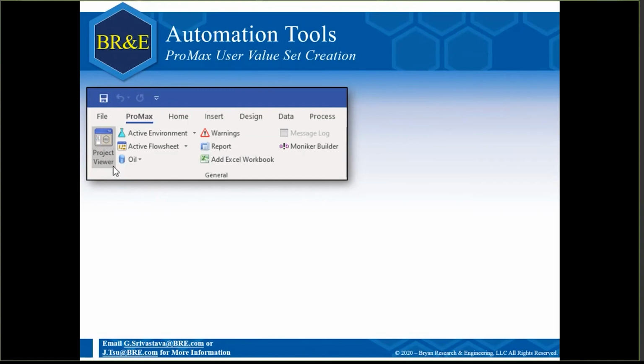We have added correlations that companies use, and even used this feature as a control panel with a bunch of if-then-else statements to change the mode of operation of a demethanizer from ethane recovery to ethane rejection. So it's a lot more powerful than what you might think it would be at a quick glance.